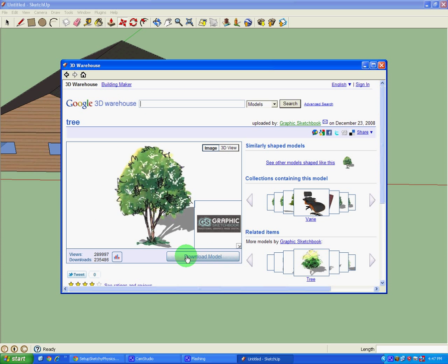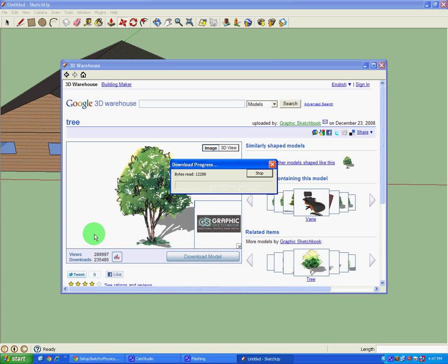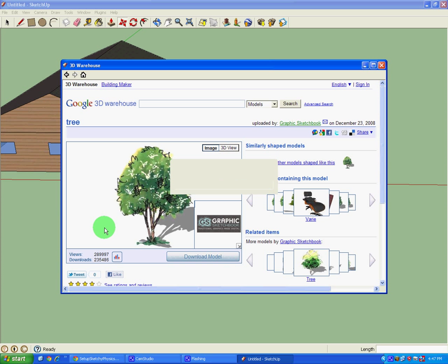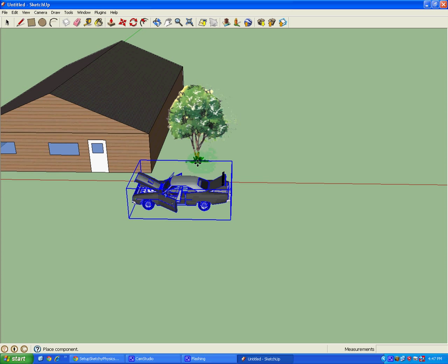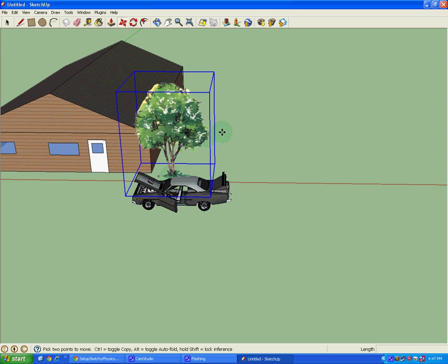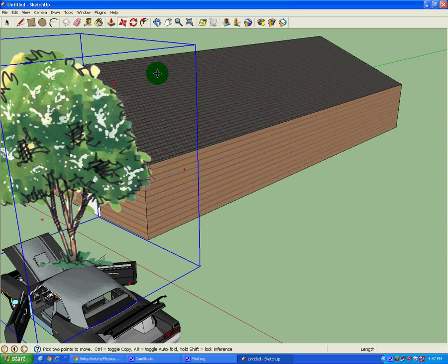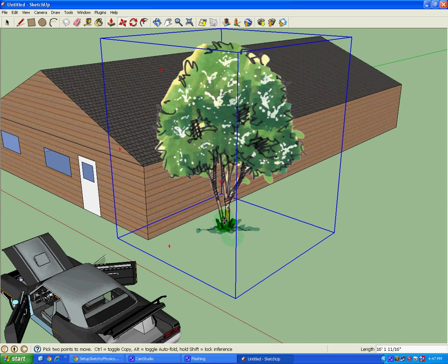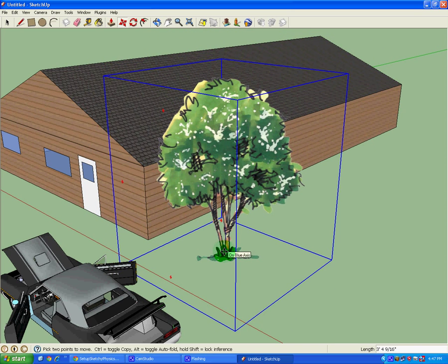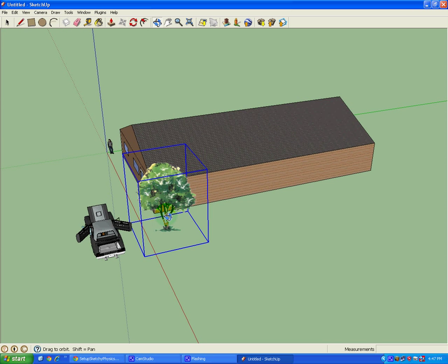Now, in the 3D model, there's no floor, though they have coloring enough for everything to stand on. Or you can draw a large rectangle, and we can color it maybe with a grass texture, vegetation, some grass. We have some grass. So now I can check, and we see my tree floating here. To get that to stop floating, if you have an object floating, grab the very bottom edge of the component and just bring it down. And I'll say on face, so now that's touching.